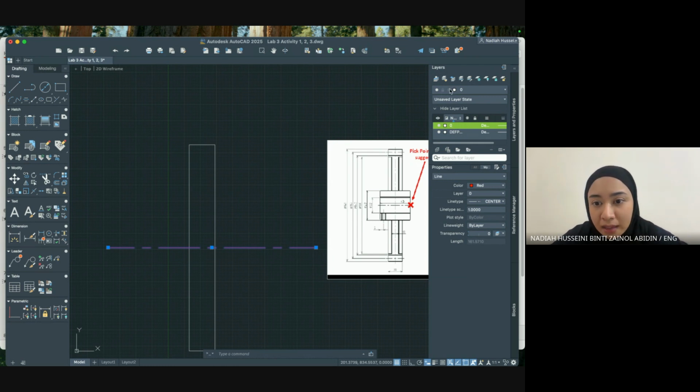And we want to add a new layer. So here we have 0. I want to add a new one. So let's see, make current, no. Layer match, no. Previous layer, no. Isolate, no. We want to add the layer. Do I right click here? I actually have not explored 2025. Is it here? Yeah, it's this symbol. So this symbol lets me create a new layer.